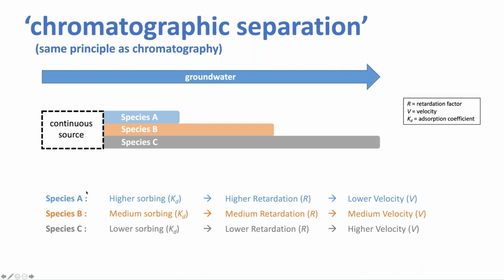And so what we can immediately see is that naturally, the faster species are going to start to move ahead of the slower species. They may all start out together like marathon runners at the starting gun, but because they're all going at different speeds or different velocities, some way down the marathon course, some are going to be arriving long before the others are going to arrive. And that means that whereas they might be bunched up in the beginning and there's lots of sorptive competition on the carbon within the barrier for them, as they progress through the barrier, that competition for the faster species reduces and reduces, and therefore the KDs are going to change, and therefore the velocities are going to change, and therefore the modeling outcome is going to be inaccurate if we don't take account of that.